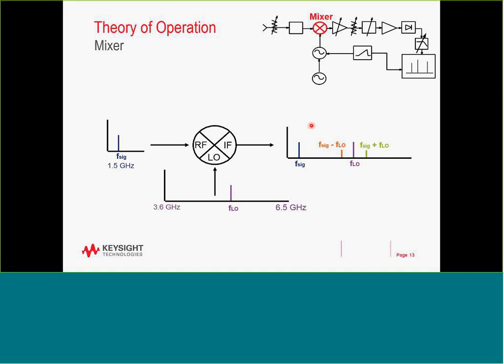So it's not a filter that is moving. The resolution filter is fixed. It's really by sweeping this local oscillator that we make the signal move and go through the internal filter. I have a little animation later on that I'll show you.